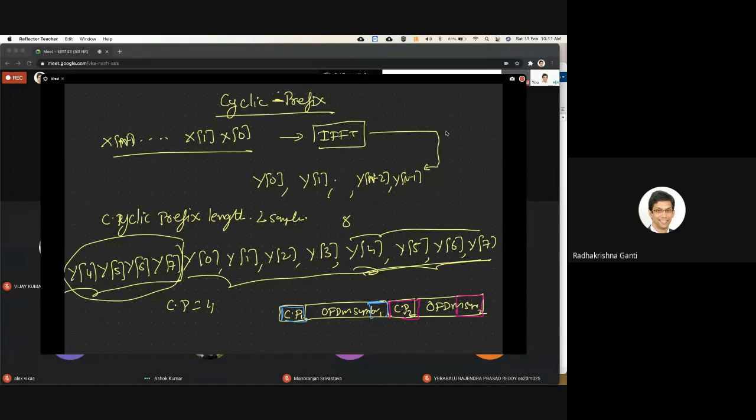Different kind of CP, that cyclic prefix. Different length, you mean? Yes, sir. That's also part of the standard. Generally you keep them the same. There's a minimum length that is specified in general. I think during symbol 0 we have a slightly bigger CP, and then we have the standard one later, exactly. That's correct.